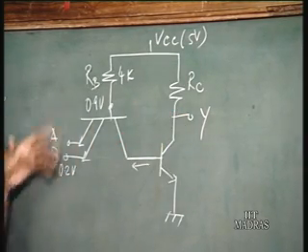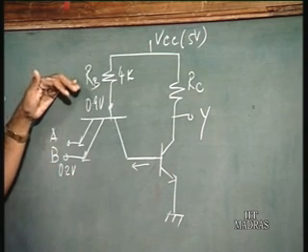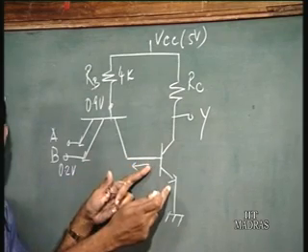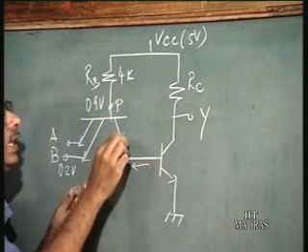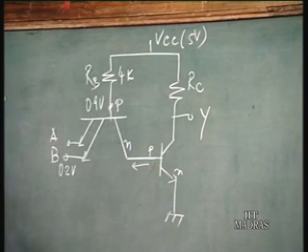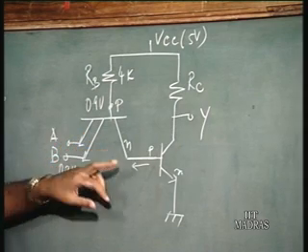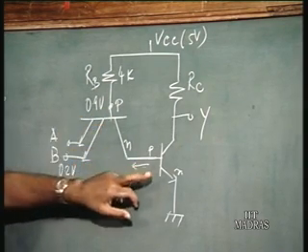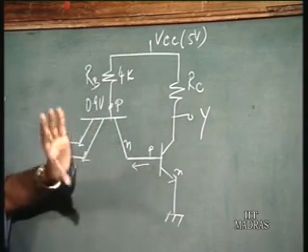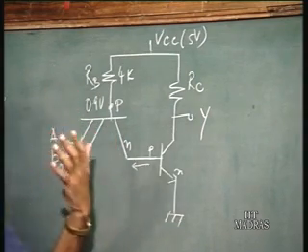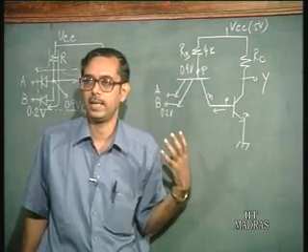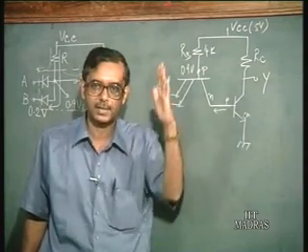Now, when both the inputs go high, when you raise the input, what is going to happen is, you see, this is a PN junction here, and there is another PN junction. This is PN, this is another PN, and this is NPN. Now a PN junction cannot be forward biased by more than, say, 0.75 or a maximum of 0.8 volts or so. It cannot go beyond that because of the nature of the characteristics of a PN junction.